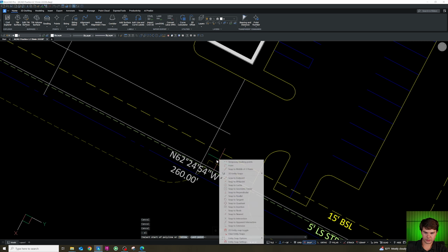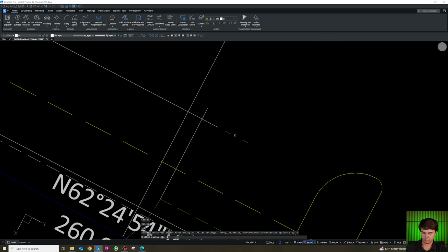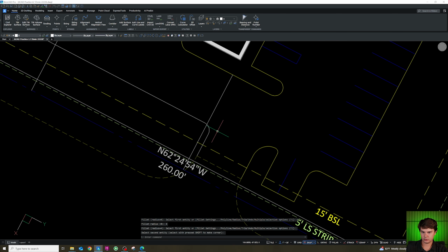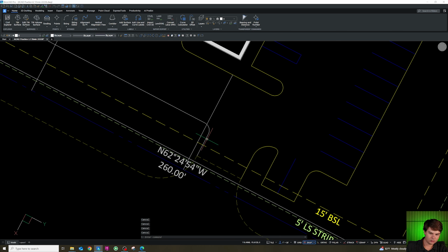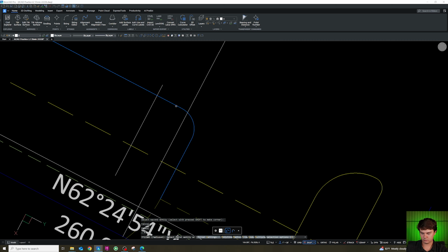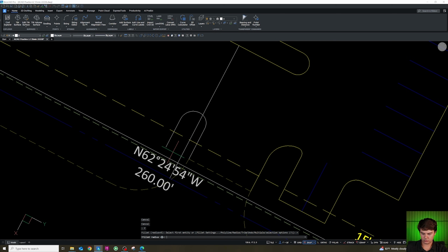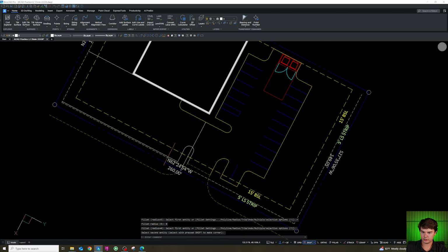And we want to make sure this drive aisle connects straight from the existing with a 4-foot radius. But before I do that, I'm going to offset, looks like a 9-foot island. And this will connect the 0 radius.